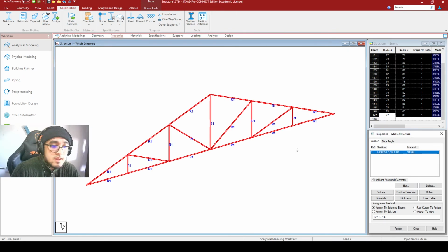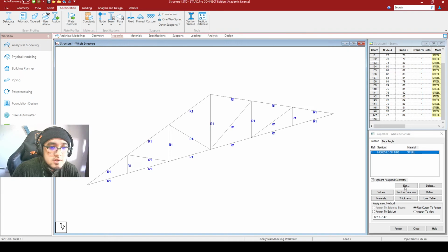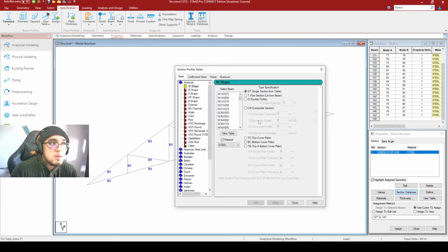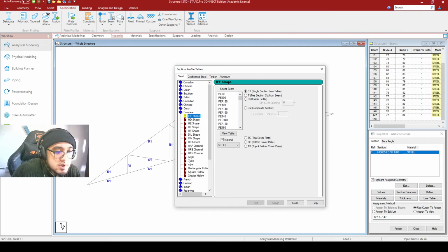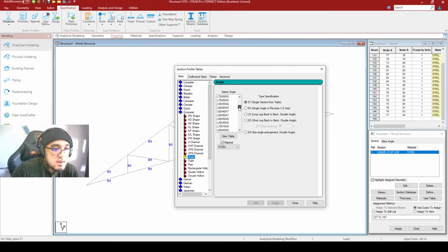So what I did here was just to assign my steel section, which is 6 by 6 by 5 over 16. So that is for the AISC shapes database. But for example, you want to have a certain section with metric units in it, what you will be doing is going to the European code, since Europe uses metric units. So once you go to the European code, go to angle, then basically it is already here.